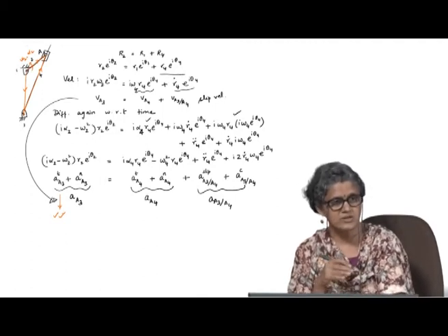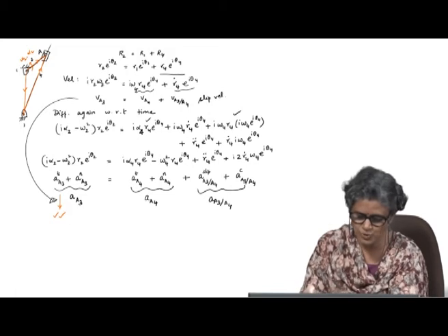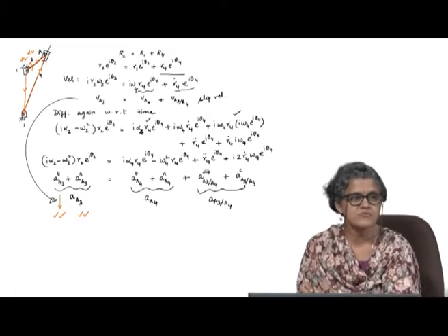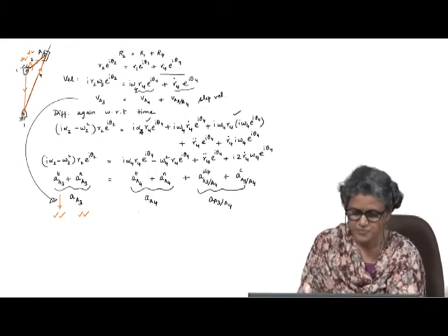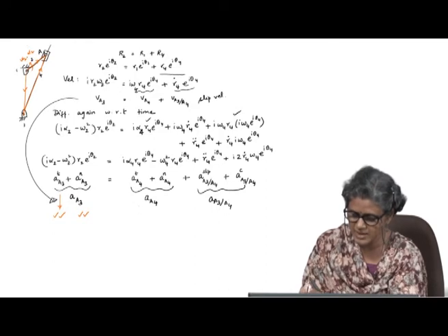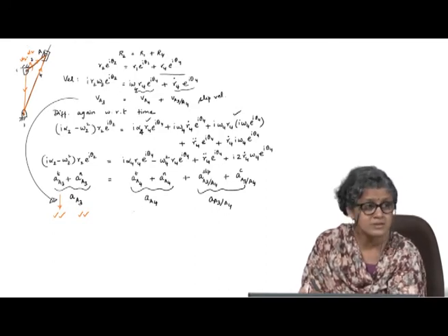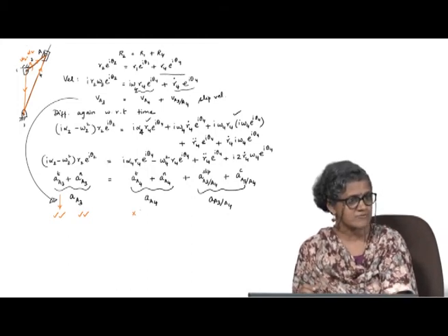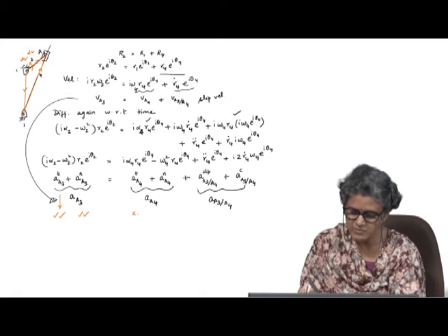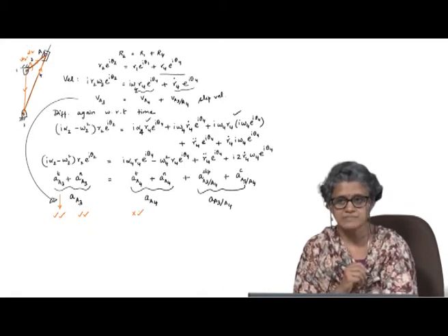The direction is perpendicular to the link O to A. This one, again the normal component, is completely known from the velocity analysis. In the case of A on body 4, again for the tangential component I do not know the magnitude because I do not know alpha 4. Alpha 4 is not known, however, I know the direction. It is perpendicular to the link.